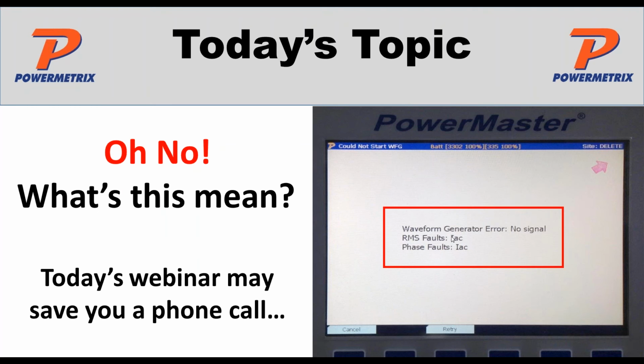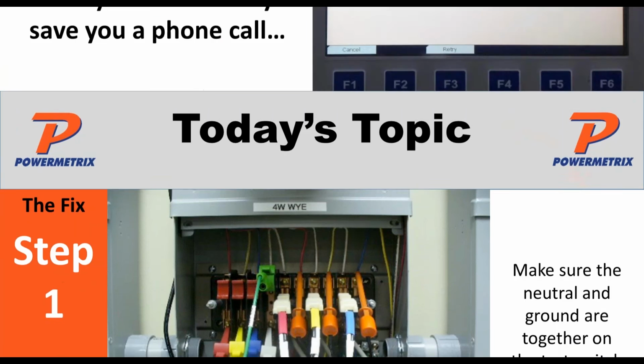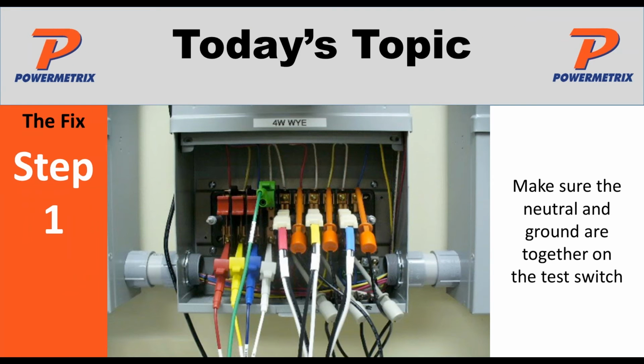So after this process, of course, you'll get us starting the load box if we don't get a waveform generator error. No signal RMS faults IAC, phase faults IAC. So what does this mean? So we're out in the hot weather and we're trying to test and we get this error, and more than likely there's probably a customer behind you looking over you to see what the results are from the meter test. So today I hope I can save you a phone call and see if we can get a couple of fixes for you out in the field.